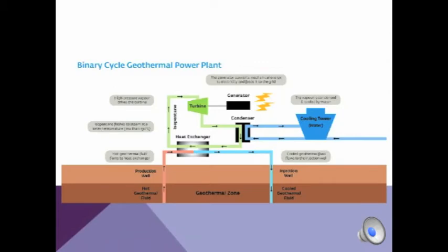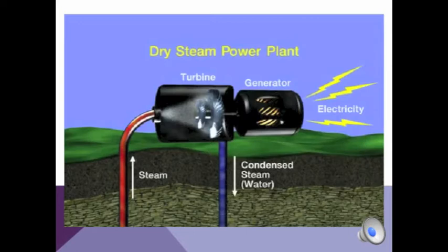Most geothermal power plants are called flash steam plants. The hot water flashes into steam when it is released from its holding cell. The pressure is used to turn a turbine. The steam is then condensed back into water and reused. Some reservoirs produce predominantly steam and little water. These are called dry steam plants. The steam is shot directly through a rock catcher where small rocks are caught, into the turbine generator.